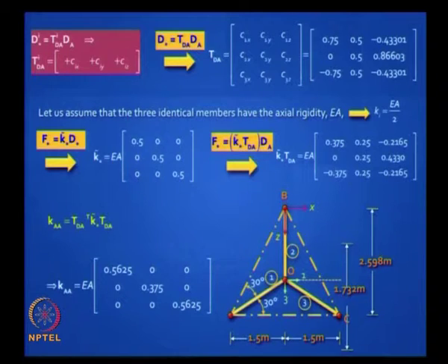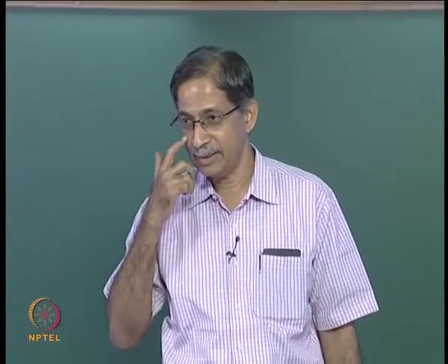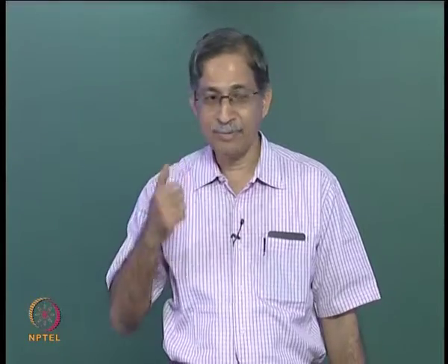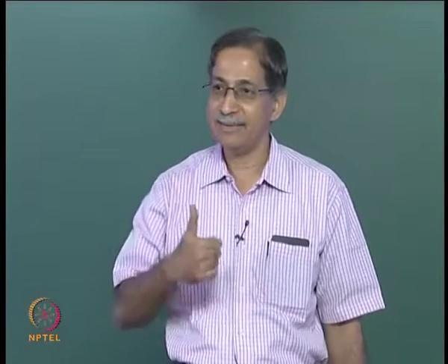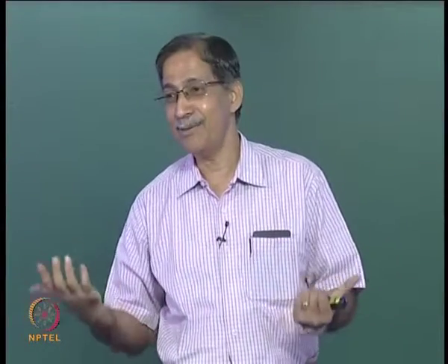No. No. No. So you won't get a force K23, you won't get a force K23, agreed? Because vertically there won't be any reaction. And sideways, will it be partial to one side? No. So you get K13 equals 0. So intuitively you know, yes, it is going to be a diagonal matrix, and so it makes sense. Is it clear? It is good to do these checks.